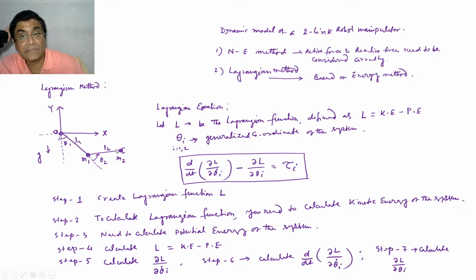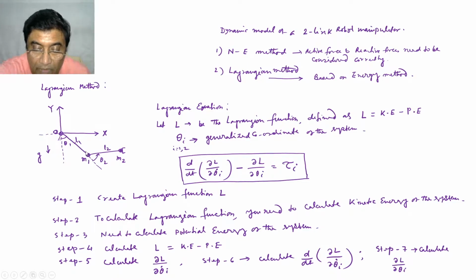Actually this can be relaxed if you have finite element software to model, but you will hardly achieve much in doing so, and you will definitely invite complexity. So that's the reason we are assuming that the lumped mass is concentrated here.